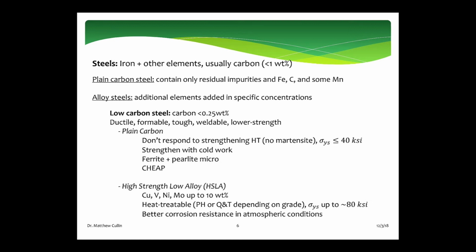And as a result, when you look at these HSLA steels after they've been exposed for a while, you say, oh yeah, there's a little bit of rust on the surface, but it's generally a nice uniform rust. A lot of people even think HSLA steels have a sort of industrial look to them, but the idea here is that the corrosion rates on them are significantly less than your plain carbon steels. And so if you're going to build a steel structure outside and you're comfortable with it getting a little bit rusty, having that sort of industrial chic look, you're going to go for HSLA steels.